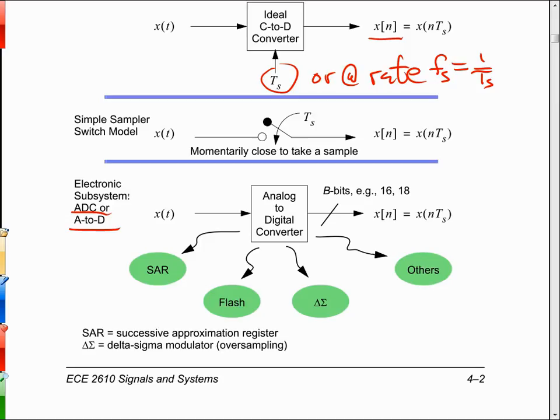More memory needed. If you're sampling at, say, 44.1 kilosamples per second, which is the CD standard, and you're sampling at 16 bits per sample, then the amount of memory piles up in a hurry. If you could cut it down to less samples, that would be nice. But what's the disadvantage of not having enough bits per sample?